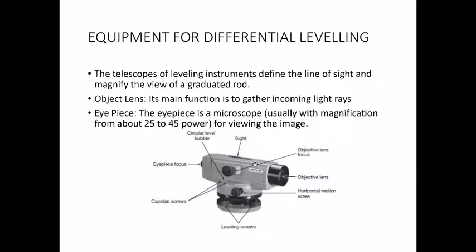And then we have this sight above. Over here you get a magnified view, but in a large view, it is sometimes difficult for you to locate your leveling staff. So in order to set the direction of this whole equipment, you can first view through this sight, which doesn't magnify the image, because you just want to locate your leveling staff. You don't need to note down the reading, so you don't need magnification.